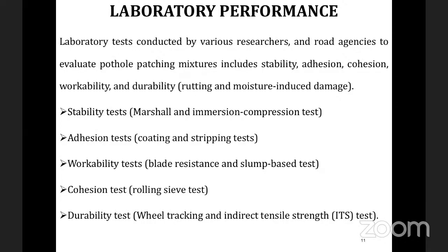Nowadays, workability can also be assessed using densification indices, based on the Superpave mix design or the Superpave gyratory compactor. We can assess the workability using the compaction densification index and the traffic densification index. The compaction densification index is a direct measure of workability. If the compaction densification value is lower, it is more workable. If the compaction densification index is more, it is less workable. So that is also one of the parameters we can look into in order to assess the workability.